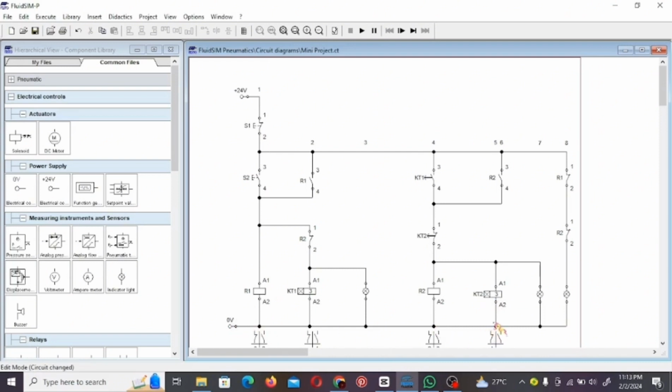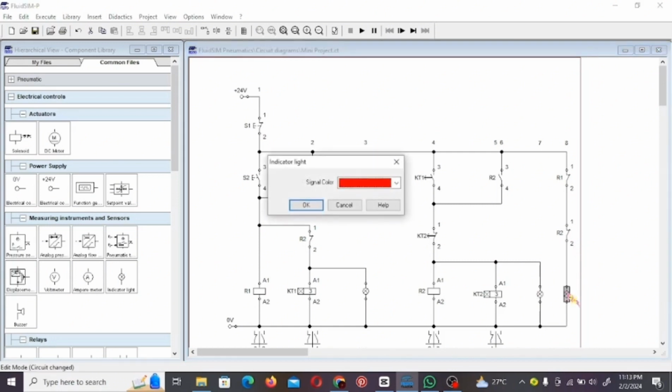Then from contactor timer 2 normally close, we connect to LED 2 such as LED yellow. Then after that, we connect out of LED to the ground or terminal block. From in contactor relay 2 normally open, we connect to contactor normally close R1. Then out of R1, we connect to contactor 2 R2 normally close. Then out of normally close R2, we connect to LED such as LED red.